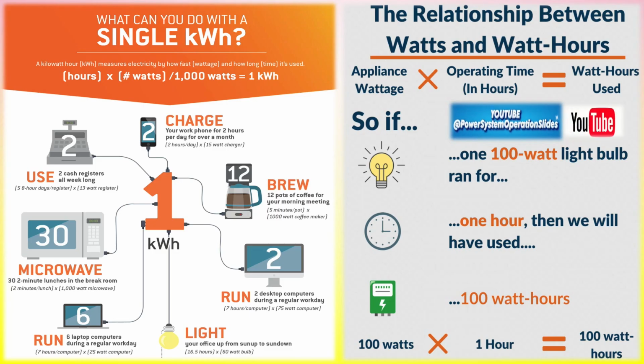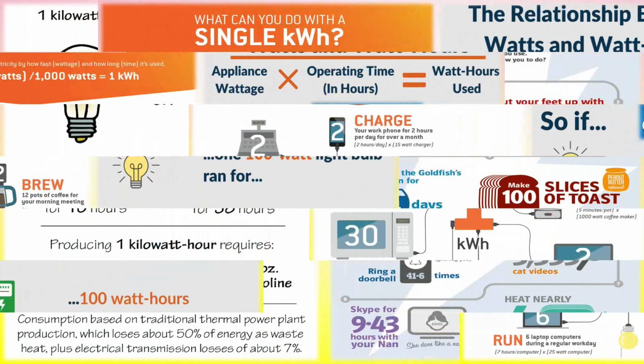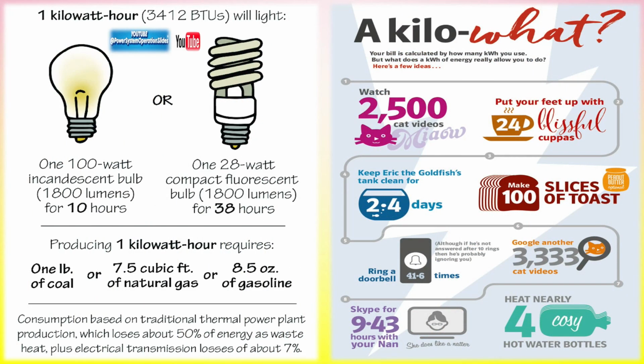Demand charges and time of use pricing. In both commercial and residential settings, utility companies may implement demand charges based on the maximum kW usage during peak periods. These charges are often calculated based on the highest 15-minute interval of power usage during a billing cycle. The goal is to incentivize users to lower their peak kW demand to avoid high costs.